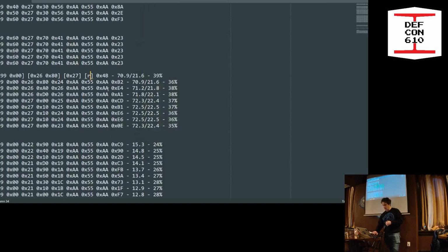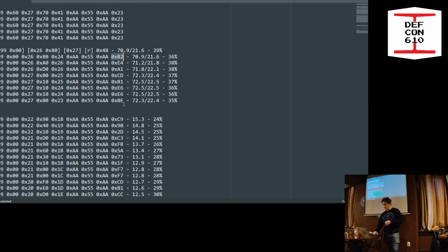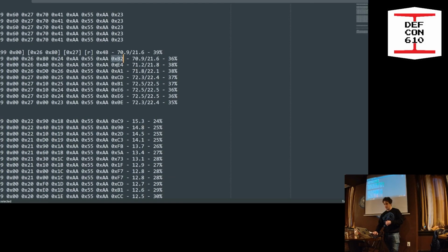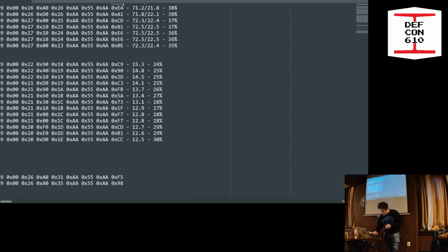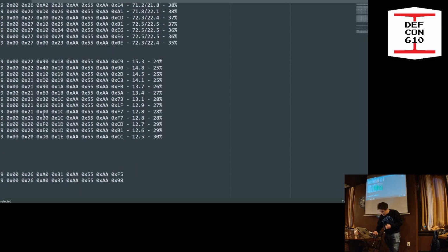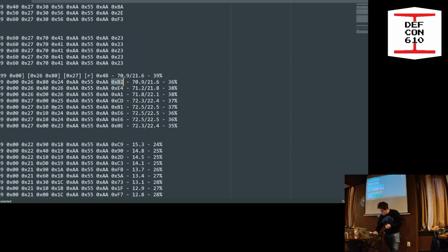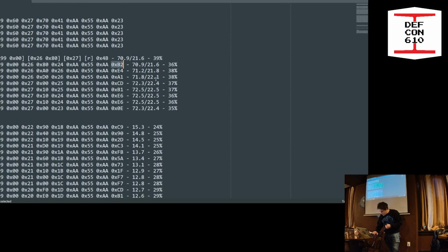And then at the end, there is a 1 byte, which changes heavily when one thing changes in it. So if we only have 1 byte difference, there's only 1 byte difference in these two lines, but the last one changes significantly, which in general means there's a CRC present.